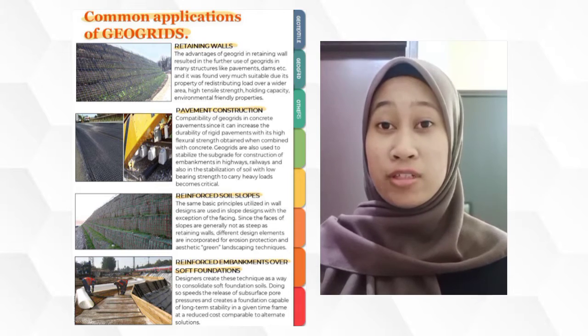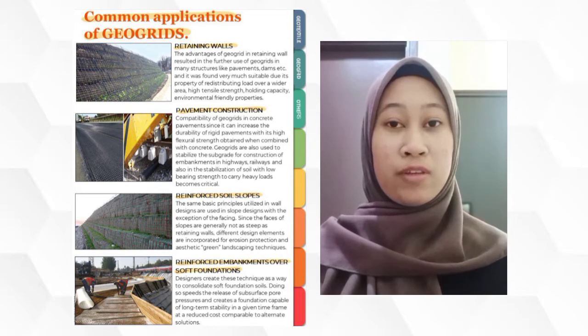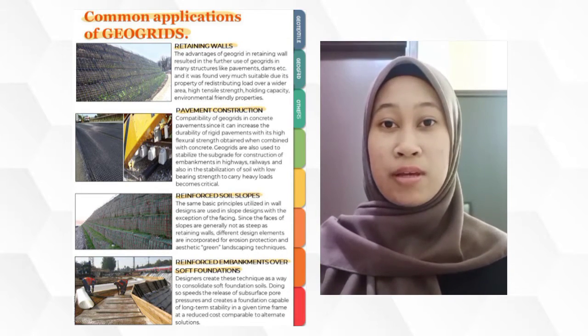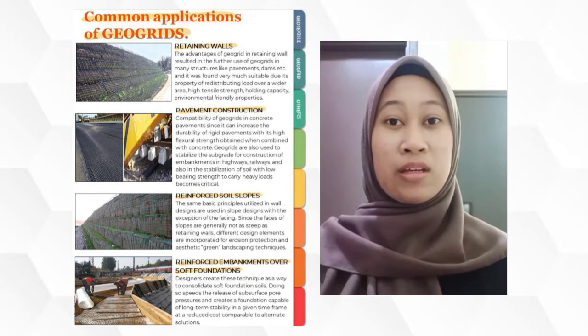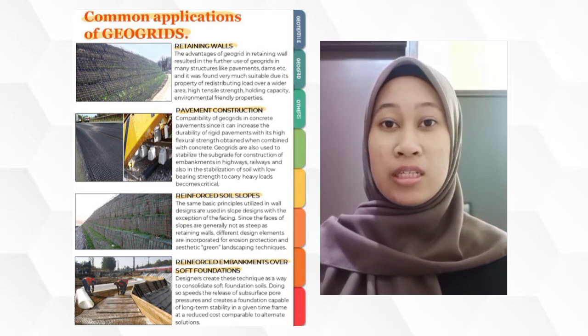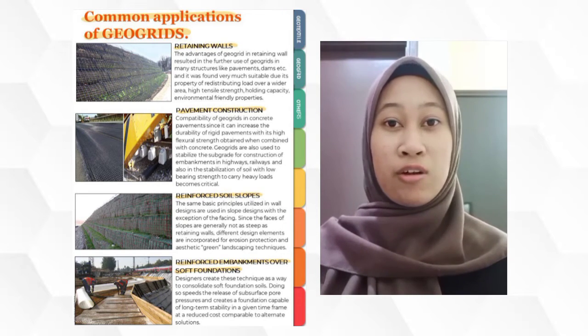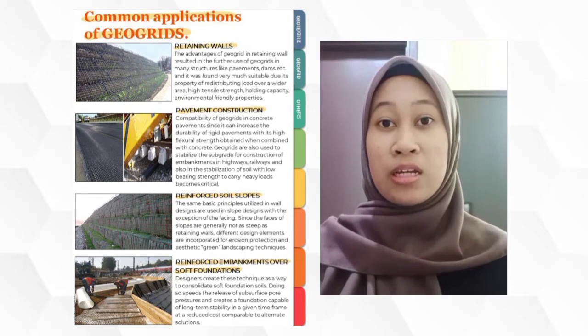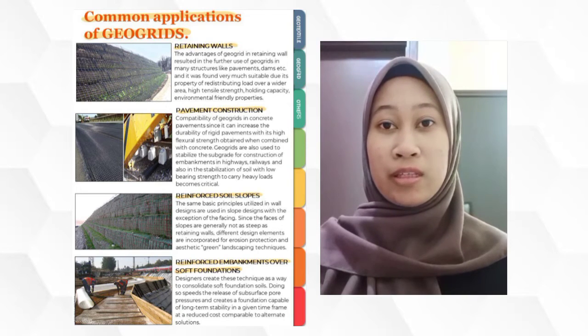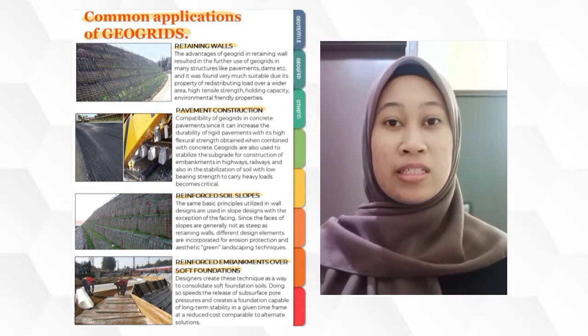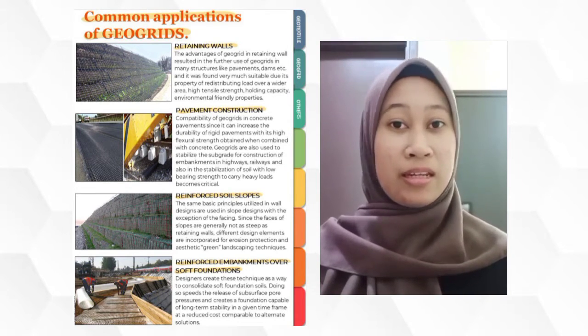Other than that, reinforced soil slopes are also one of the applications of geogrids. The same basic principle utilized in wall designs is used in slope designs with the exception of the facing. Since the face of slopes is generally not as stacked as retaining walls, different design elements are incorporated for erosion protection and aesthetic green landscaping techniques.